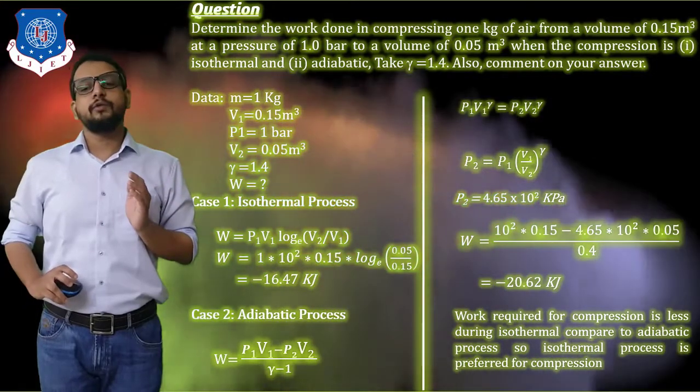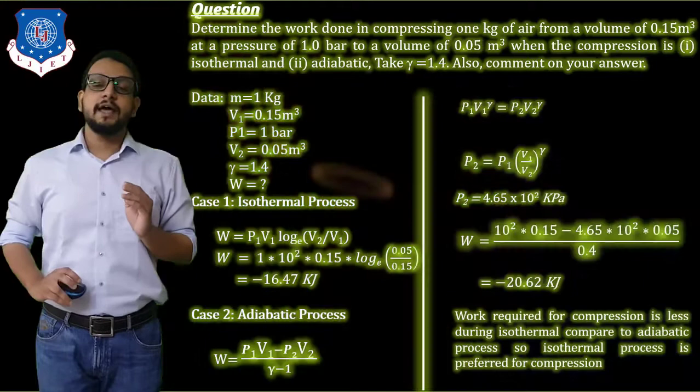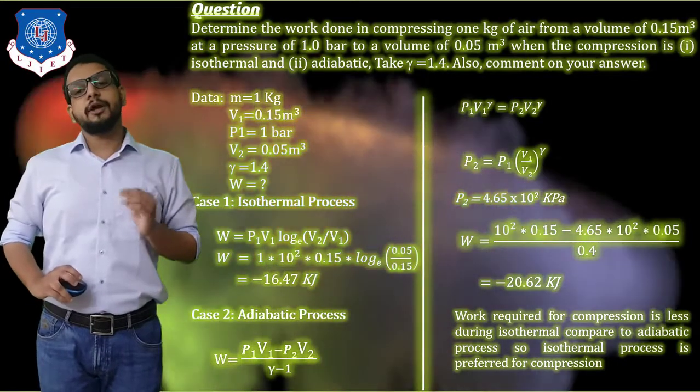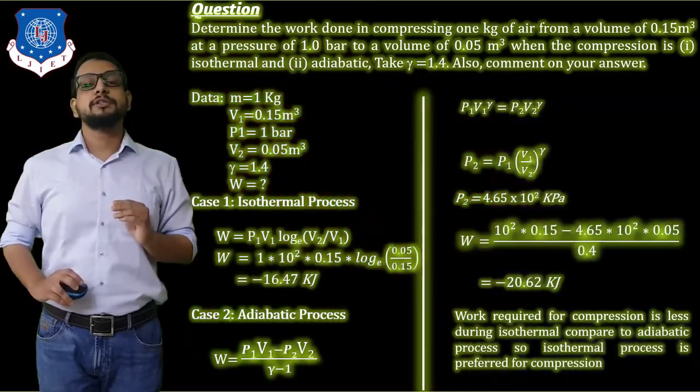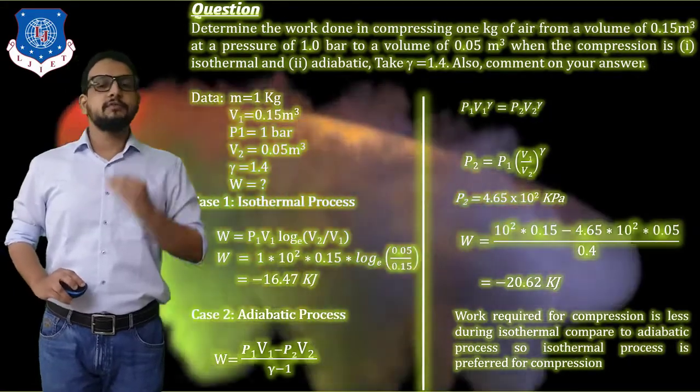So we can conclude that work required for compression is less during isothermal process compared to adiabatic process. So isothermal process is preferred for compression. So this is our final answer.